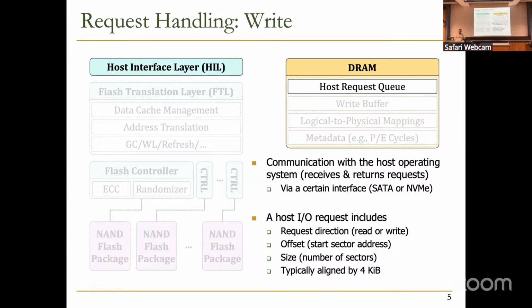That sector is actually a conventional name coming from HDDs, if you know about it. There we had this sector, and we could read sector by sector. But people still use that definition when they work with SSDs, for compatibility reasons. So we need to inform the SSD about the offset that we want to write to or read from. And also the size, like how many sectors you want to write or read. The total size of that request should typically be aligned to 4 kilobytes, because of the page size we have, which is usually 4 kilobytes.